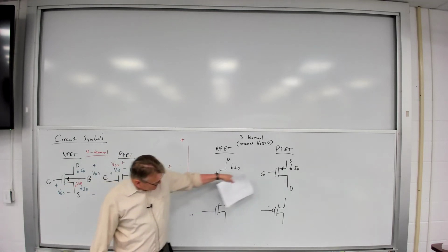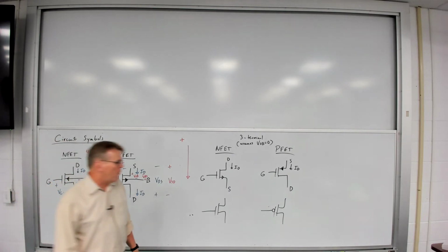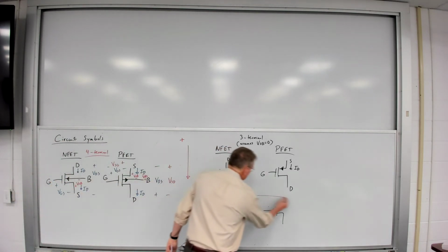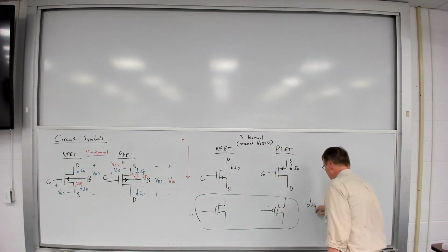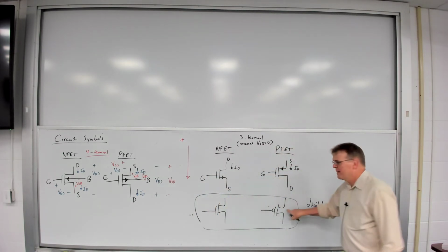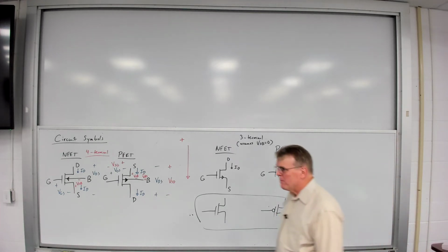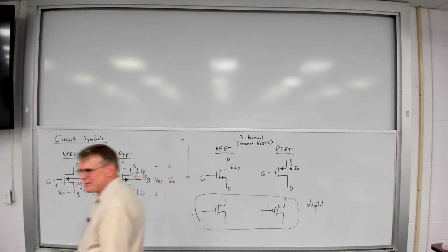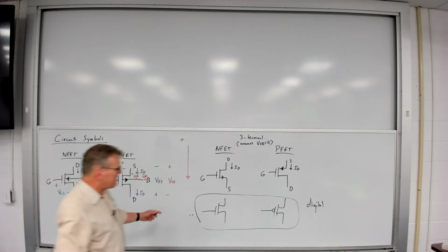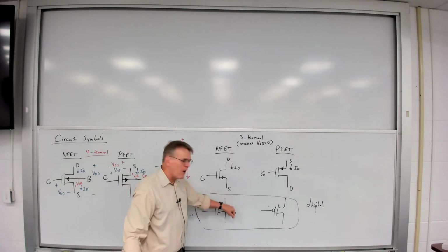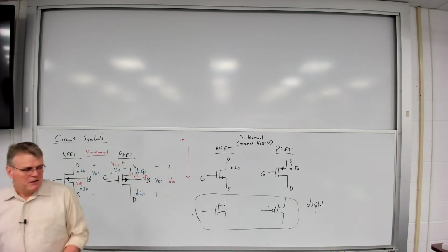This type of schematic drawing technique, you'll see used a lot more in digital design. So you'll see some manufacturers do this. Incidentally, what does that bubble remind you of? Anybody who's had digital systems? Yeah, it's an inversion, right? So what they're saying is the same voltage applied to a gate turns on an NFET, turns off a PFET. So that's the not symbol. So you'll see this too.